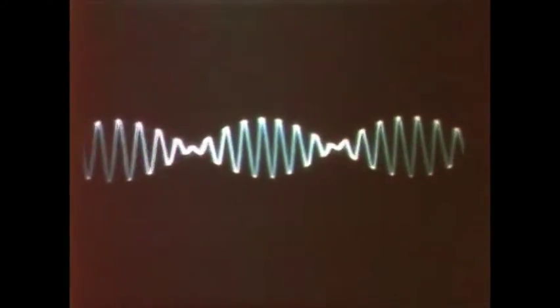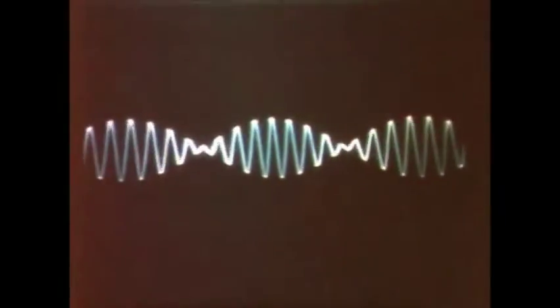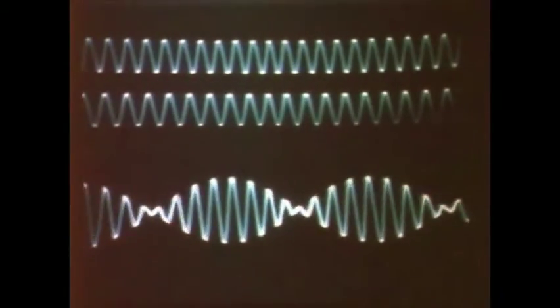We know that in this simple situation, these wave groups are made up of only two waves. So if we measured the heights and the frequencies of the waves in these groups, we could mathematically resolve them back into those two waves that we started with. And that's how we'd find the energy of the wave group. In the sea, the situation's more complicated, but it's just the same in principle. Wave heights measured over a period of time can be analyzed into the simple waves that make up those real wave groups.